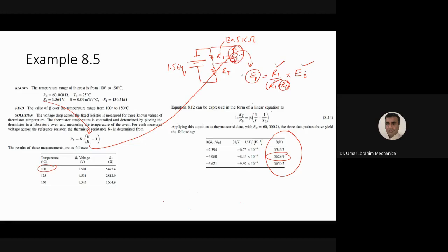Because of that, you will incur some error of measurement when you try to measure some temperature with the thermistor sensor, because you are using a single constant beta value provided by the manufacturer instead of a beta value for a specific temperature.